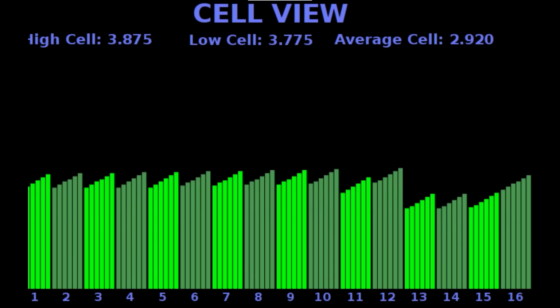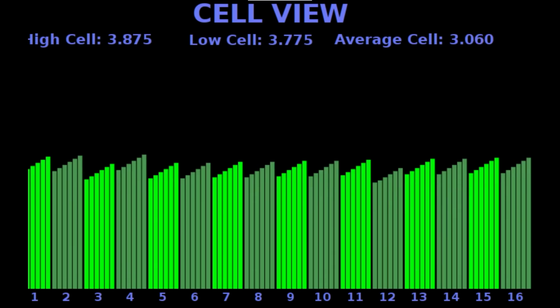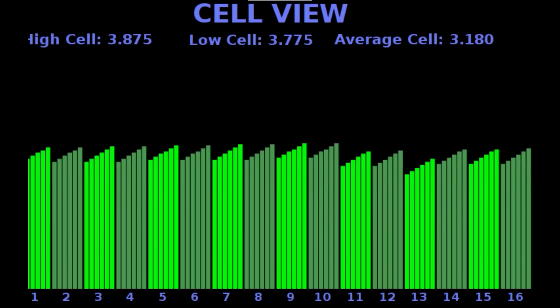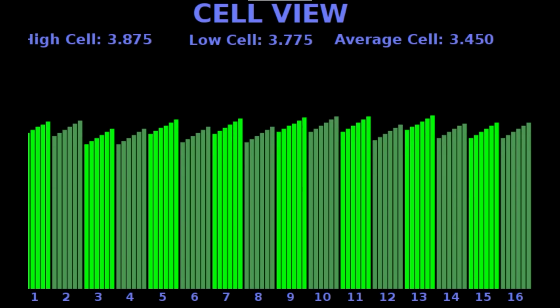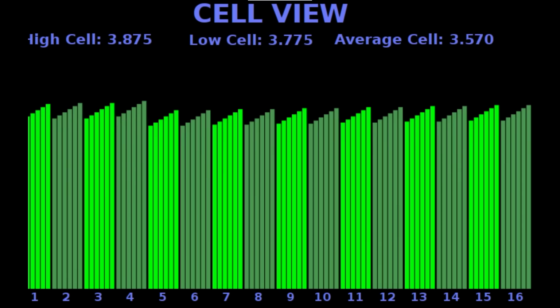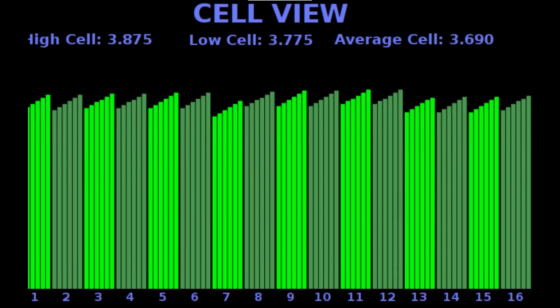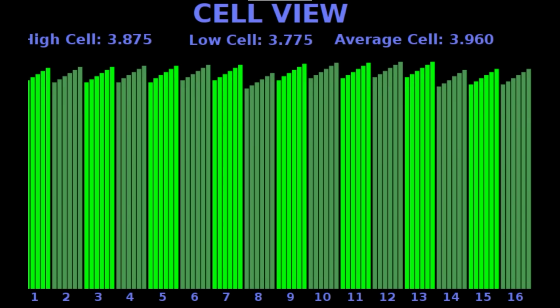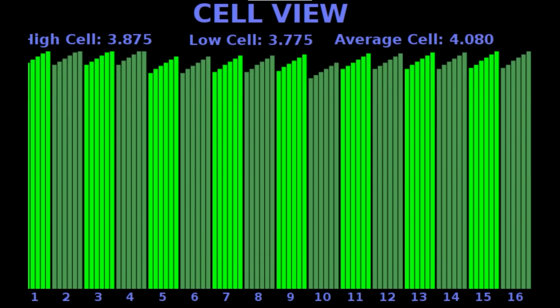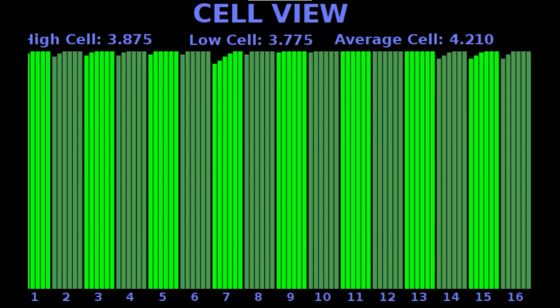This is not a 100% connection. UDP packets are connectionless, and there's no error checking or retransmission. So we're just blasting these packets and receiving them as we get them. This is kind of an interesting data philosophy, but it's very similar to CAN. In a car, you can have 30 devices on one CAN bus, and they're all transmitting more or less at random times. And so there are packet collisions all the time and retransmissions.